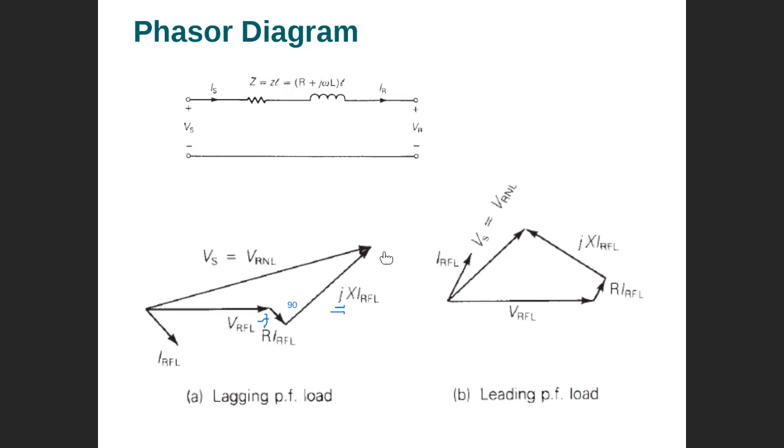How do we know? This is a transmission line. We don't write the numbers here, but as an engineer, you need common sense. You are familiar now that X is higher than R. So when you read the data and see something else, you can tell the data is wrong. Maybe the data entry person entered a wrong number, maybe 0.1 per unit for R and 0.01 for X. It cannot be like this, so you can determine something is wrong in the data. This is what engineers do when they work on planning or calculation.